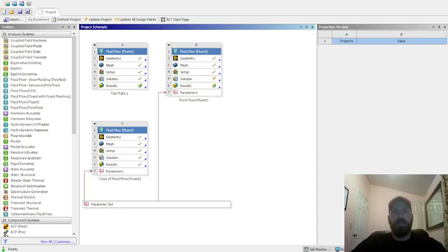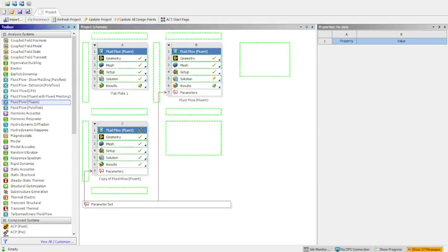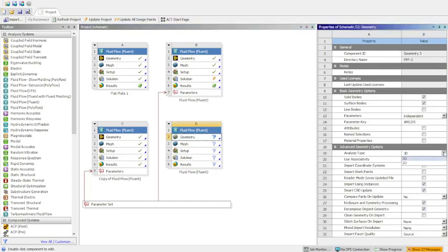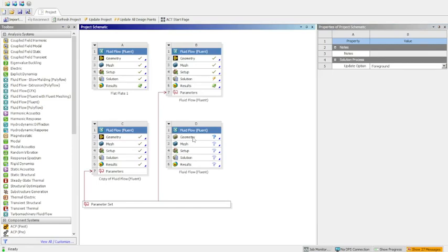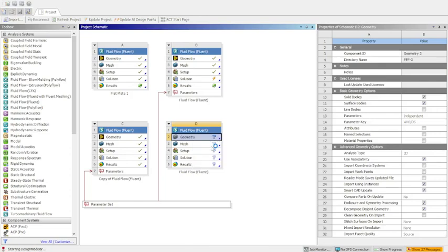As you can see, I have the ANSYS Workbench pulled up. So we are going to drag the fluid flow Fluent into our workspace. First, we will left click on this. We're only doing a 2D analysis. And then we will right click on this. I prefer to use the design modeler. You can also import your geometry from SolidWorks or use the space claim. I just prefer the design modeler.